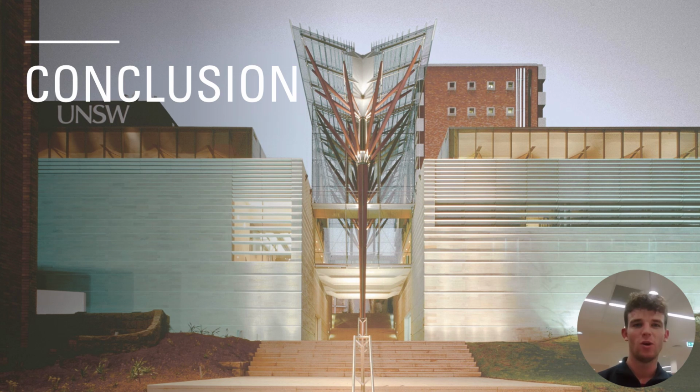In conclusion, while the key materials used in the Scientia building provide strong performance, they also create environmental challenges. Precast concrete contributes to high embodied carbon, and aluminium panels require energy-intensive production. However, alternatives such as geopolymer concrete and fiber cement panels can significantly reduce environmental impact while maintaining performance. Overall, this shows how informed material selection can improve sustainability while still preserving the building's design and function.